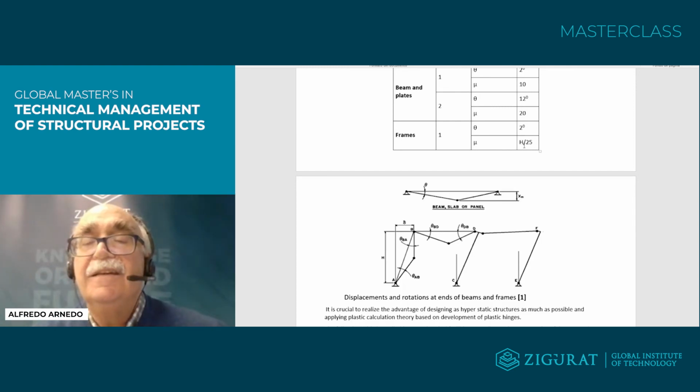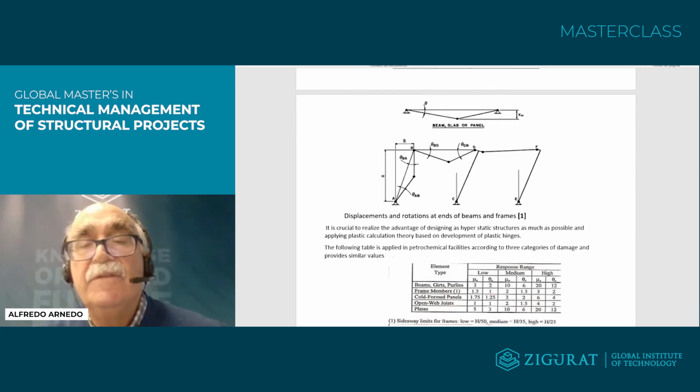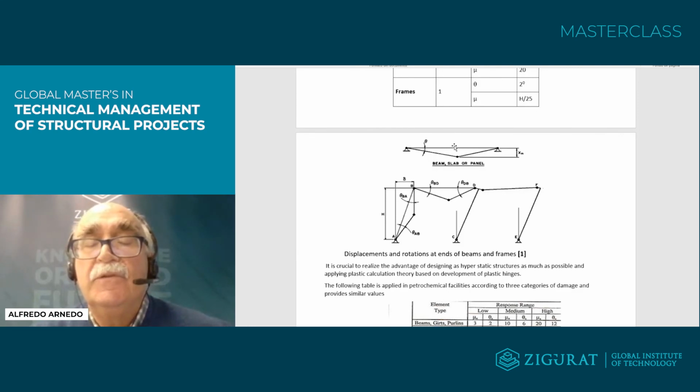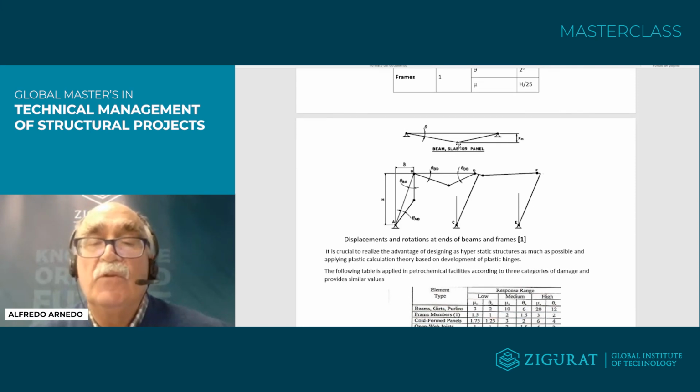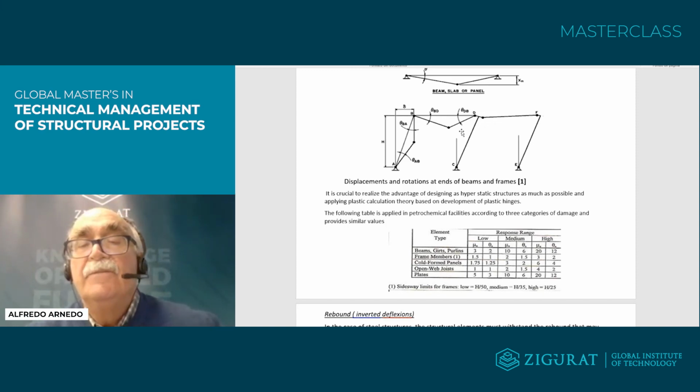In the last stage, when the failure happened, we can admit the height of the building divided by 25, something very, very extreme, very important. Of course, at the end, the structure has suffered a ruin, but it has coped with the requirement to resist and to defend the properties or even the people. Here is the figure. This is the behavior in the plastic range of the structure.